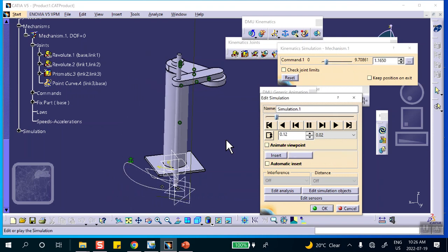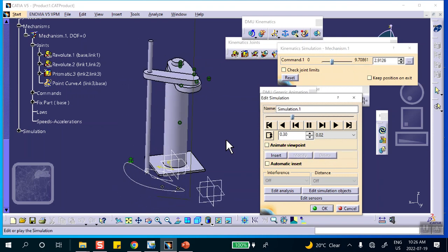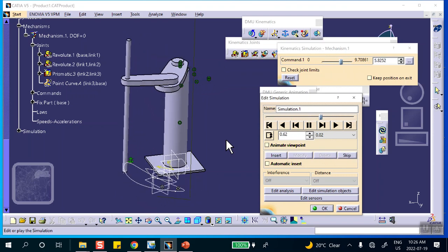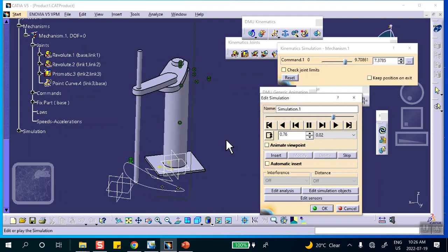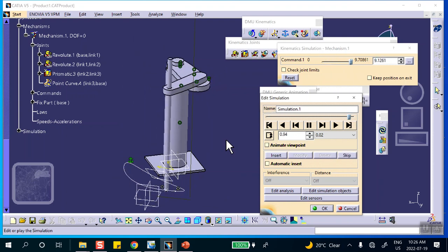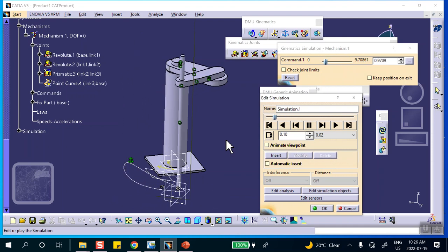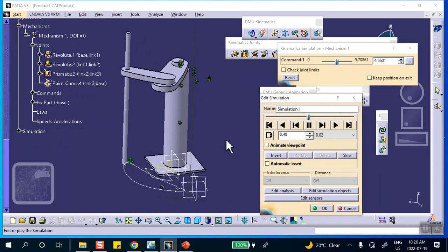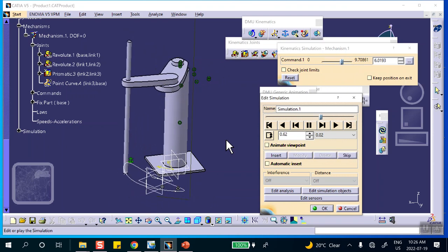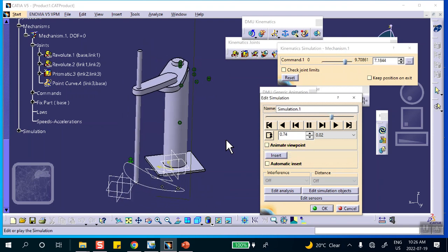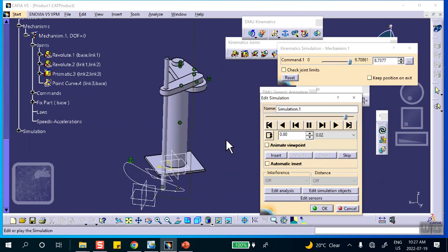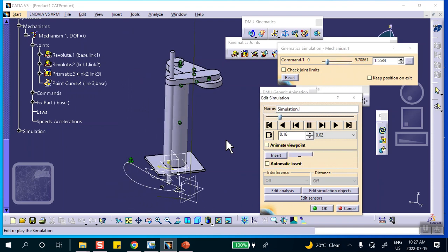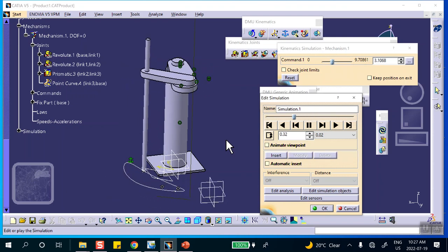If the answer is yes, why are you falling off the horse? If you're falling off the horse, it means that there's something acting on you, on your mass. There must be an acceleration. The tangential acceleration is zero, not the normal one. The normal acceleration is not zero. And in fact, you have a formula for it from high school physics: V squared over R. If you know the velocity, the speed of that point, and if you know the radius of curvature at that location on the curve, you have an acceleration, and it's V squared over R.